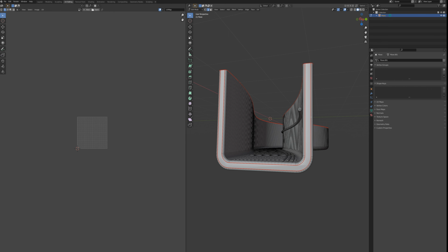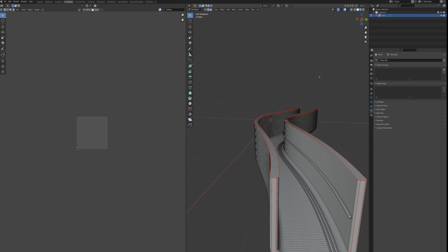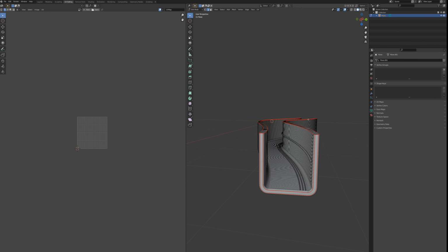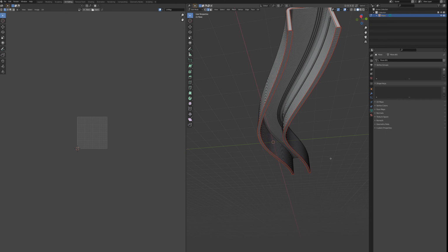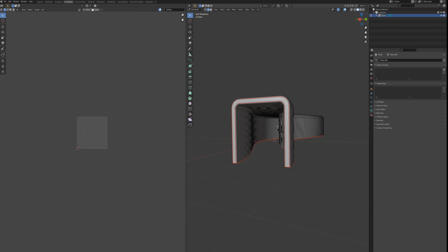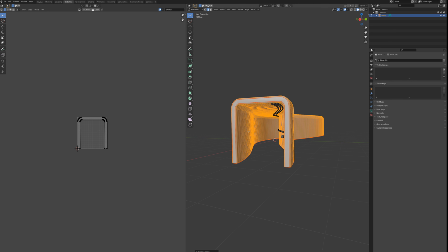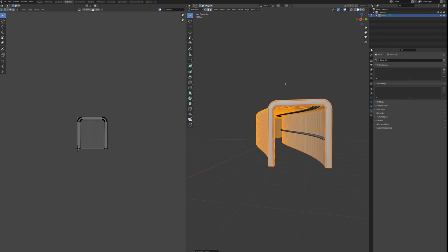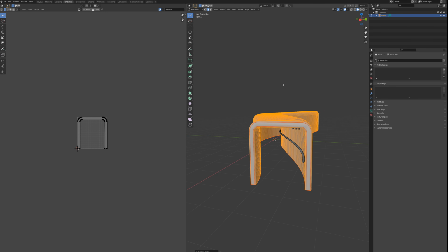And with that marked, the bottoms marked and those front faces marked, basically everything else here can be just unwrapped as it is. So I'm going to unwrap the walls, that is. We're not going to unwrap the railing or the top pipes here yet. I'm just going to press L to select the wall again, and I'm going to go to UV, unwrap.